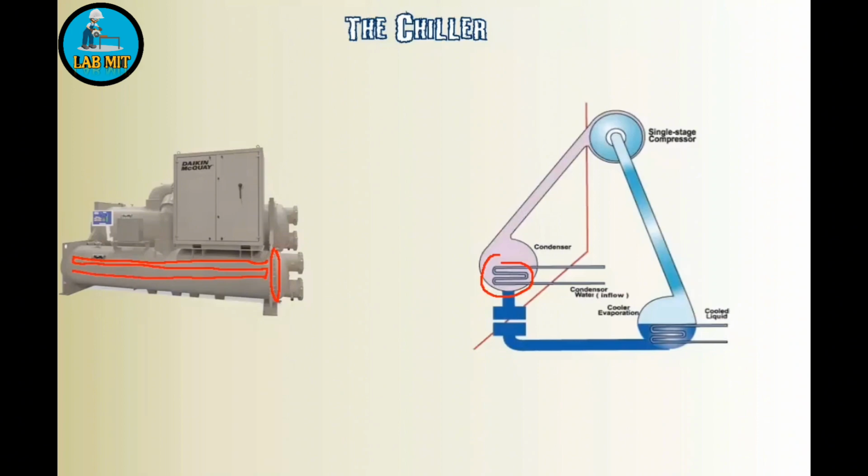And so if you ever hear of somebody saying they were changing out tubes or they have dead tubes in the barrels and so forth, these are many tubes, and there's many of them. I've seen some chiller barrels that had literally 100 or more inside the chiller barrel. So there's tiny little tubes all throughout this chiller barrel. And that's where you get the water running back and forth through this barrel to do the heat transfer. So just a little bit of extra on the chiller. Let's move on to the next step.